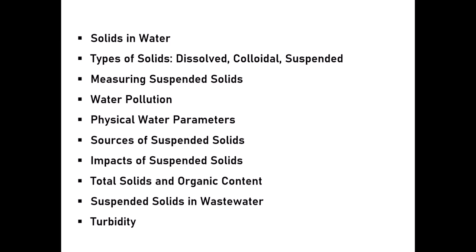And for total solids and organic content, total solids equal suspended and dissolved solids. Organic solids are determined by drying at 140 Celsius and burning at 600 Celsius. Volatile solids are burnt organic matter, and fixed solids are the remaining inorganic matter. Suspended solids are key for evaluating incoming wastewater and treatment efficiency. The EPA limit for treated wastewater is 30 mg per liter of suspended solids.